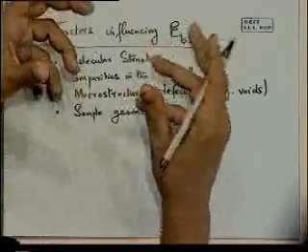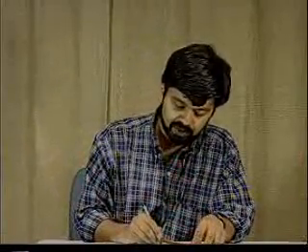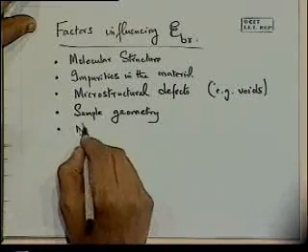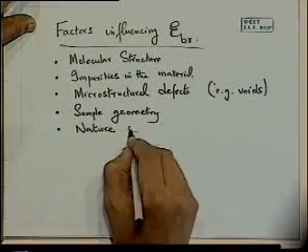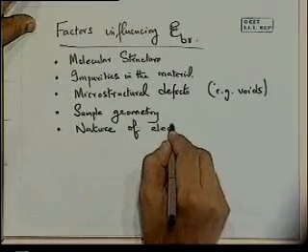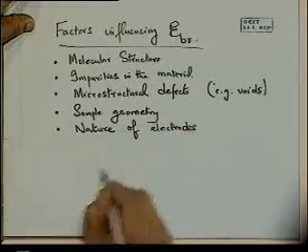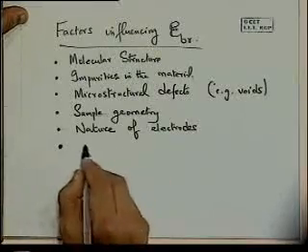What kind of shape the sample is in, pointed shapes, tips, corners, various things can influence when it will break down. Excuse me. The nature of the electrodes, whether those will begin to influence whether charge gets transported across, whether they will get damaged at the high fields. So many things could happen with the very electrodes that we are using to attach.